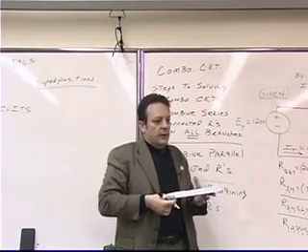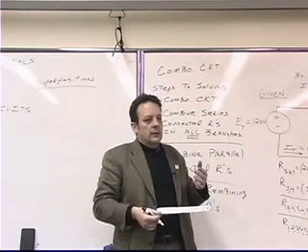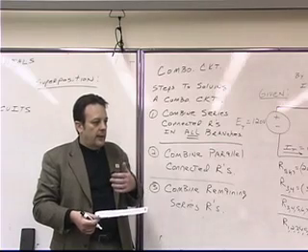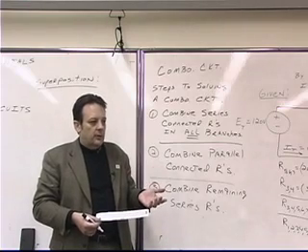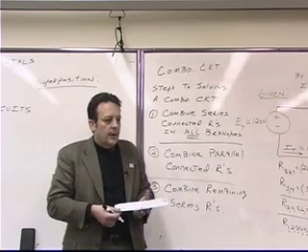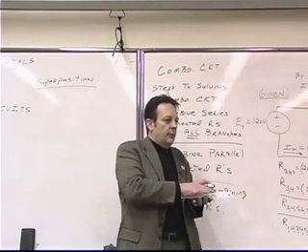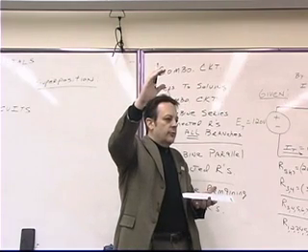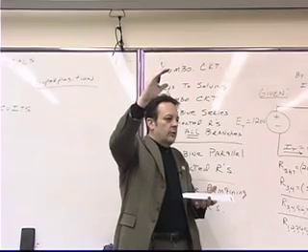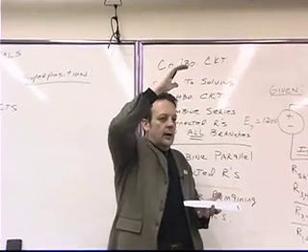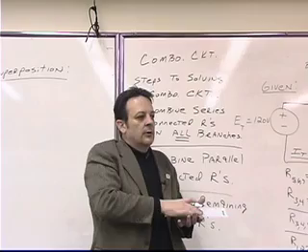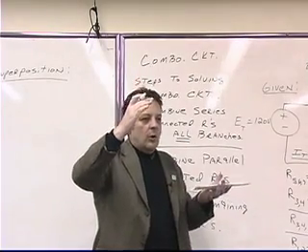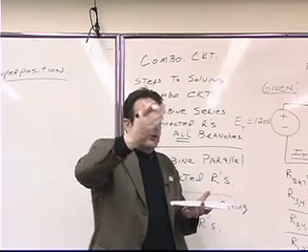So in other words, they don't combine in some kind of a vector geometric way. They simply combine algebraically. Okay? So if I had 5 foot candles from the first light and 7 foot candles from the second light, then if I turned off the first light, I would expect to see 7 foot candles, only the number of foot candles from the light that was shining.